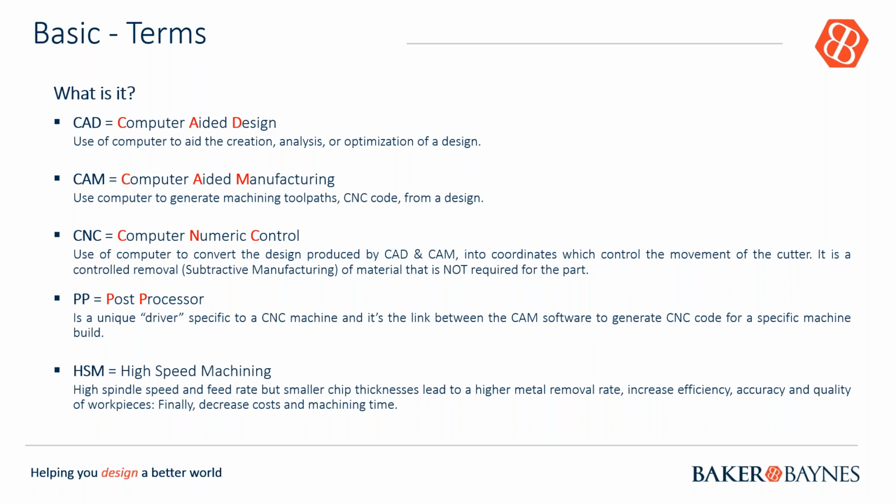Basically, you do the design, you do the CAM part of it with the operation itself. Once you're done, you post that to the machine using the post processor or the G codes, and the machine receives that, you set up the tools and the workpiece, and you're able to do the machining itself. This is part of the subtractive machining operation, so removal of material.